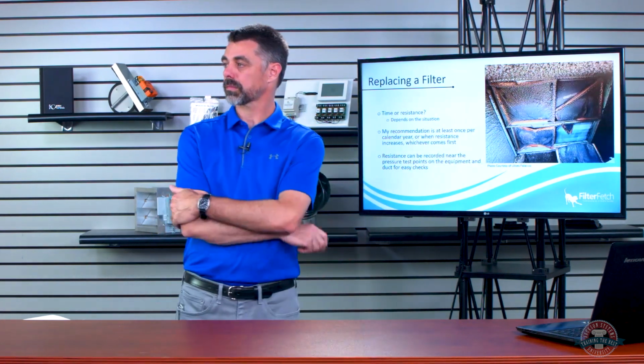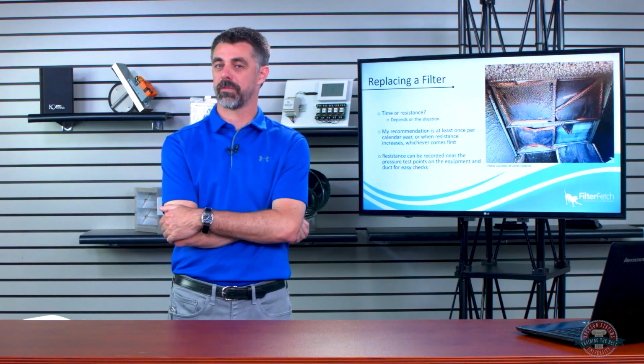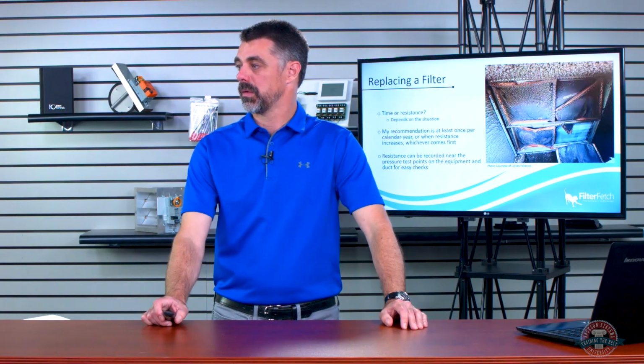Bob wants to know, what type of filters remove odor? Typically, you're going to look for a charcoal filter. Now, you want to look at the filter and what kind of charcoal is in it, and you want to find something with activated carbon in it, okay? Not just a carbon filter, because a lot of carbon filters use burnt plant matter in them, and it's really not that effective for very long. Versus if you get activated carbon, it's going to last longer, but they're more expensive and harder to find. That actually answered my next question, what the charcoal filters were.